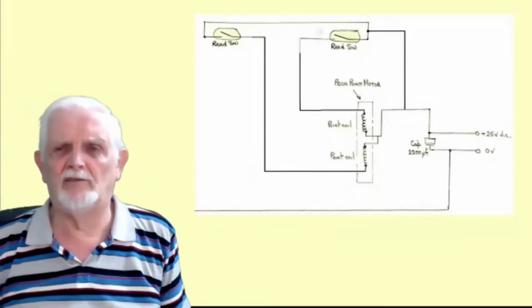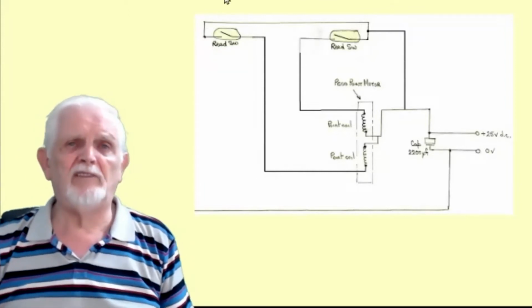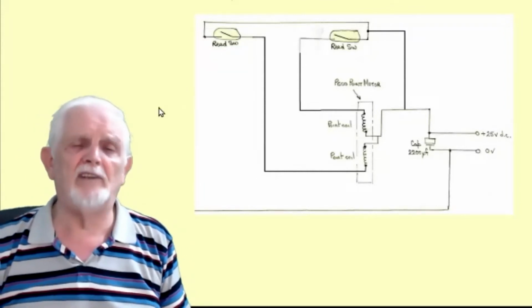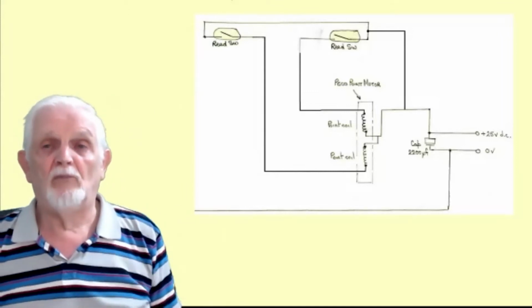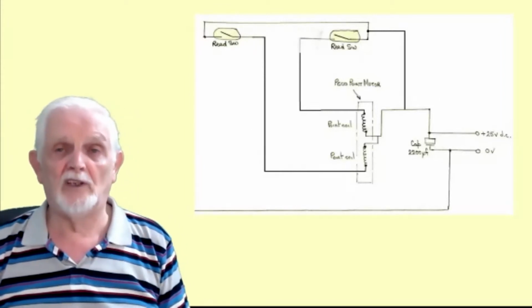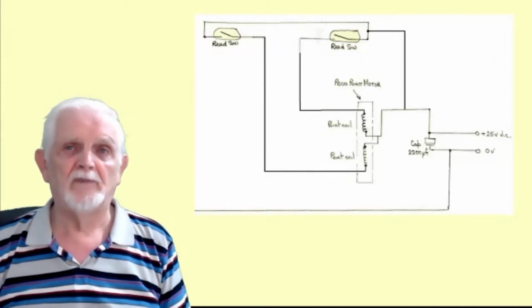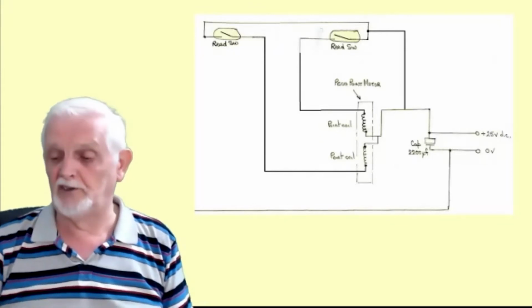And I thought that's not very good, because reed switches vary, some are like half an amp and some are 1 amp maximum current, whereas point motors, H&Ms and so on, can easily have 10 amps peak. So we don't want to be constantly arcing the reed switches.